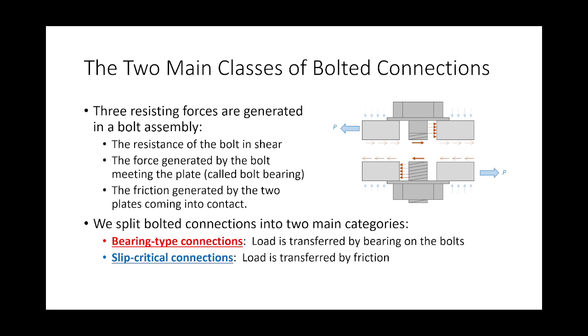We typically only use slip-critical connections in two main arenas. The first is bridges. Okay, let me explain why. How many of you have ever done any type of mechanic work with your hand, fixed a lawnmower, fixed a dirt bike, anything like that? Imagine if you have a loose bolt and you turn on the engine, what happens? It falls off, right? Now imagine if you have a somewhat loose bolt on a bridge that's up for 75 years. See what I mean? Load, unload, load, unload, load, unload for 75 years. You can start to see what's happening, right?